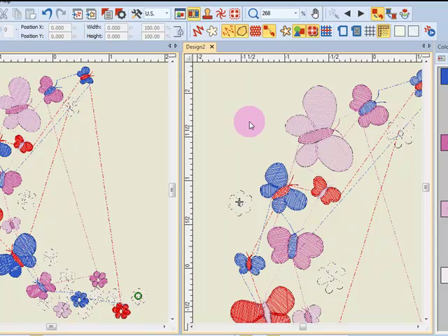Sometimes objects are on top of objects and it's hard to get the part that you want. If you are wanting to select a layered object, hold down the number 2 key on your keyboard and click, and continue to click without moving the mouse, and you will get the layer that you want.